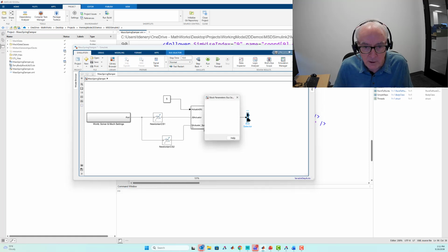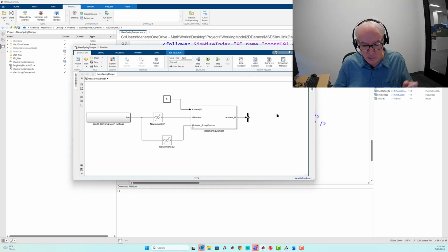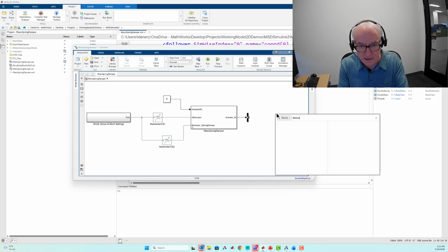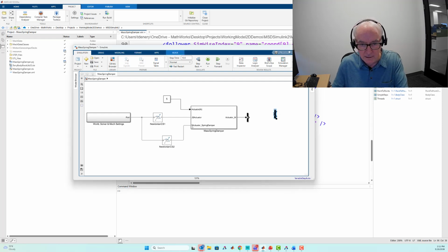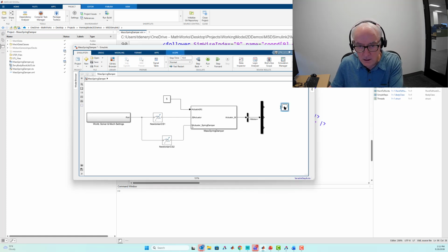The export creates a measurement on the actuator that provides motion, force, velocity, and power. Select motion. Motion could be one of these PVA things, so we need to unpack that. A PVA is going to be three scalar signals: position, velocity, and acceleration. And so we get that. Let's put a scope on position, and let's hit run.